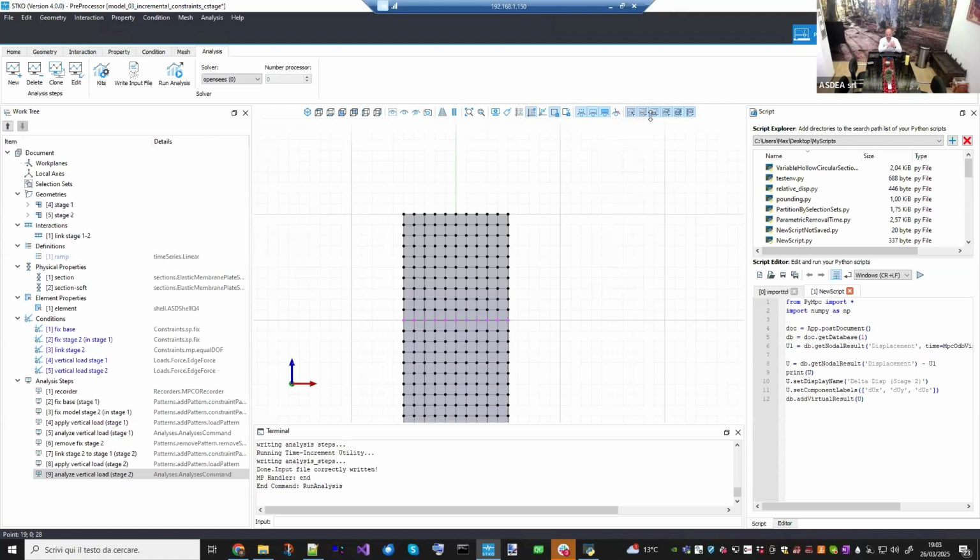But many other times they applied all the constraints correctly, but the constraint handler is not able to apply them. And the problem with the transformation handler is that OpenSees does not warn you that one constraint has not been applied. It simply skips that constraint, and you will realize it if you look at the results and see that some part of your model is floating.